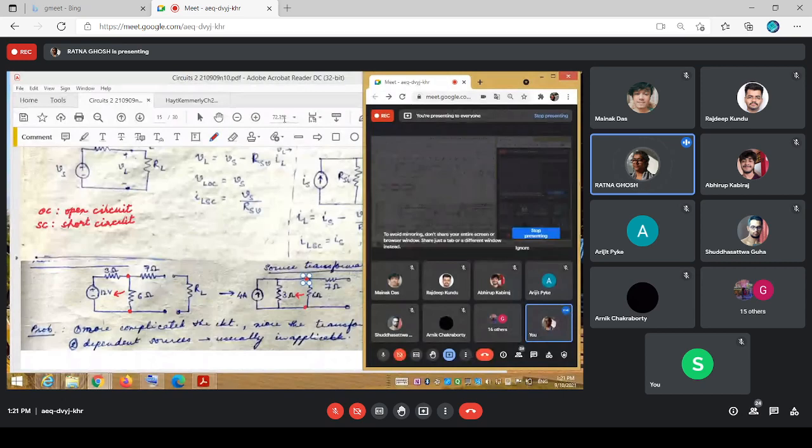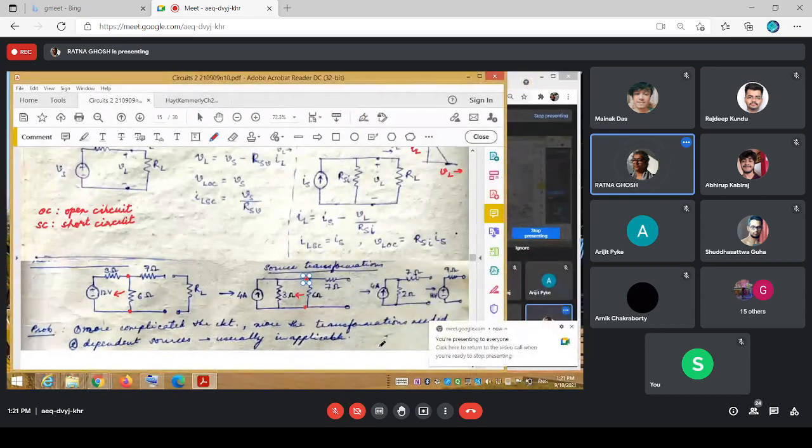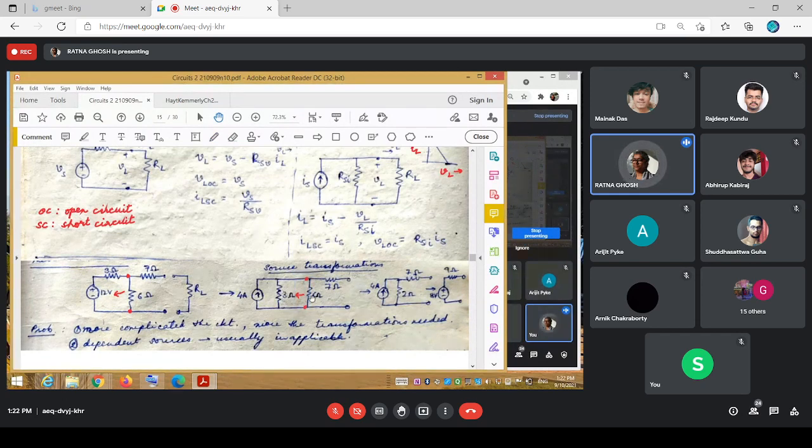Okay, so I hope you got a chance to look through this one a bit. So that's the equivalent: 12 volts, 3 ohms, that is the 4 amps, 3. And this is now a parallel combination of 3 and 6. That's nothing but 2 ohms.